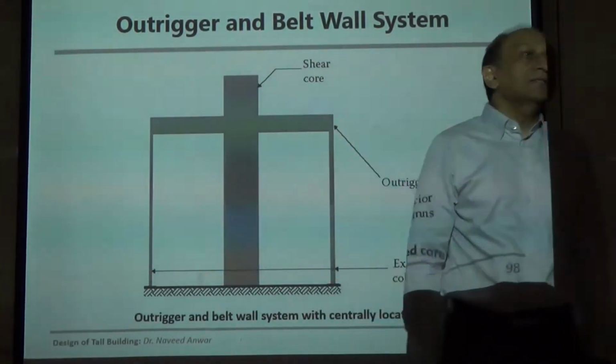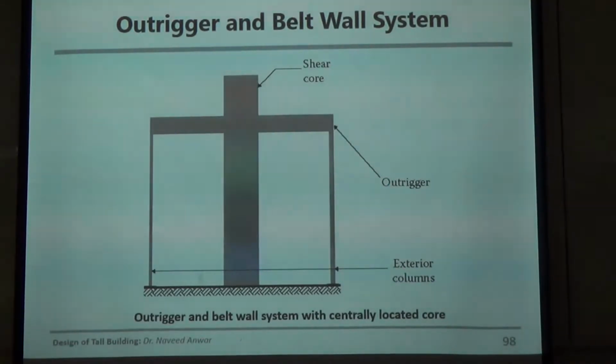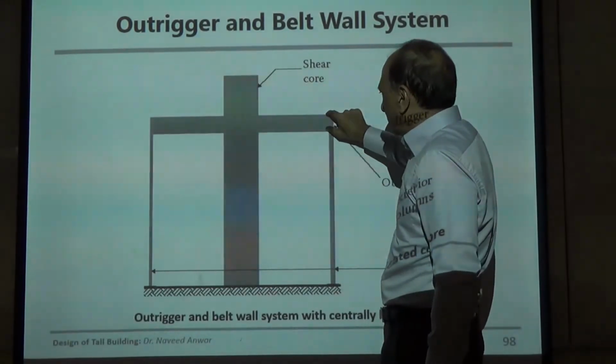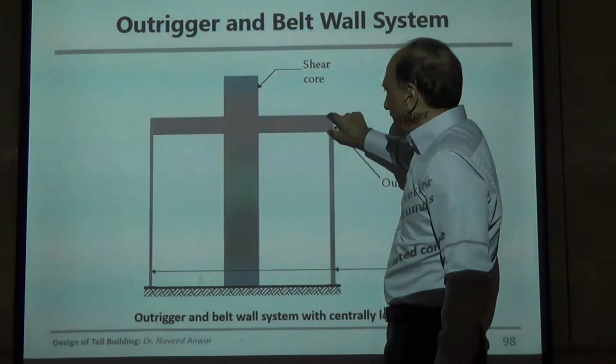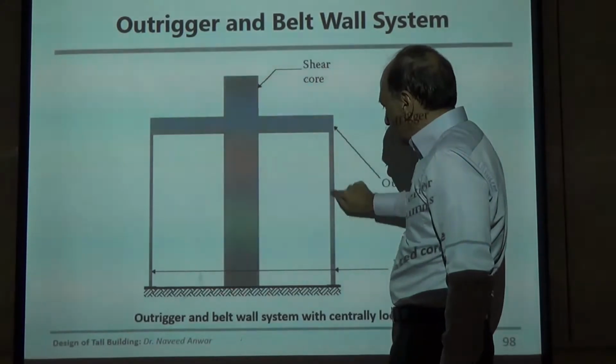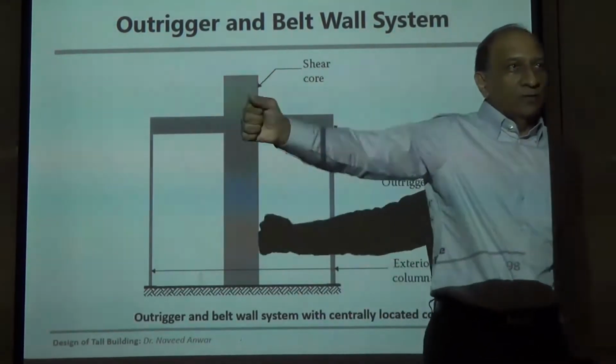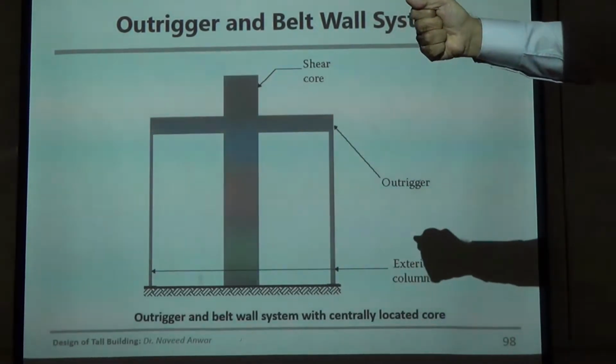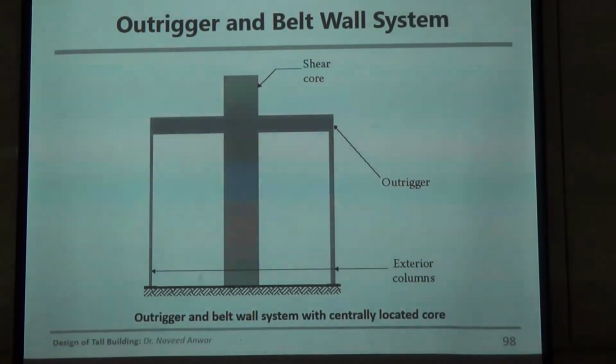Same as the coupling, but not used on every floor, only used on some locations but very deep. Basically from the core wall we create a big cantilever or a big beam and then connect it to the column. Same thing that we did earlier, but now it is longer, very far, but very deep, right?